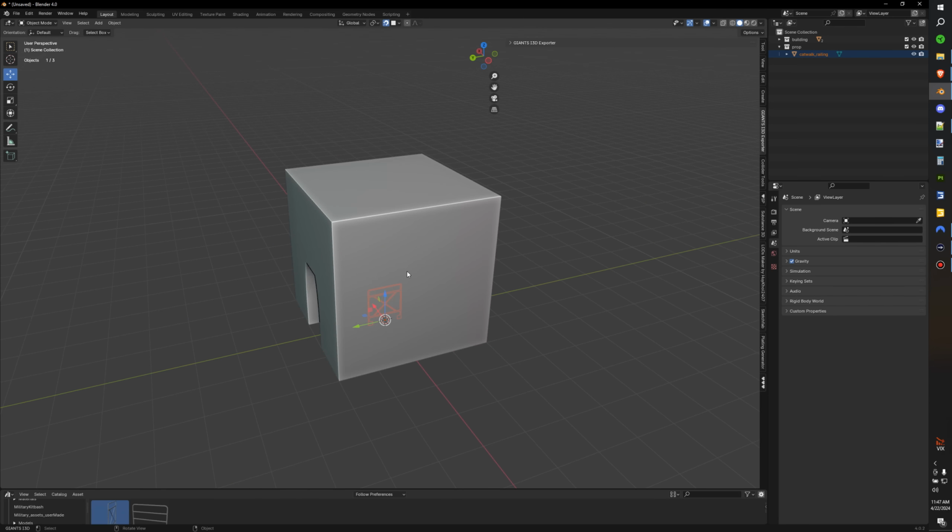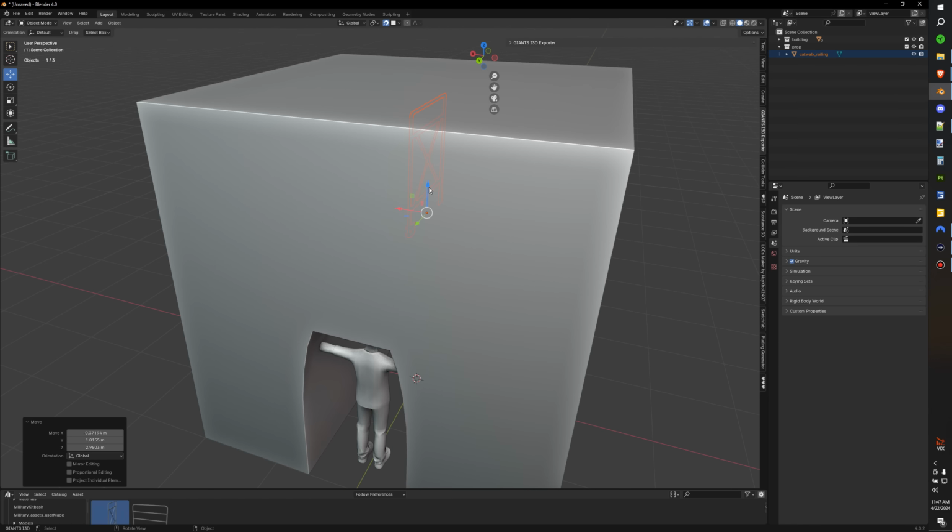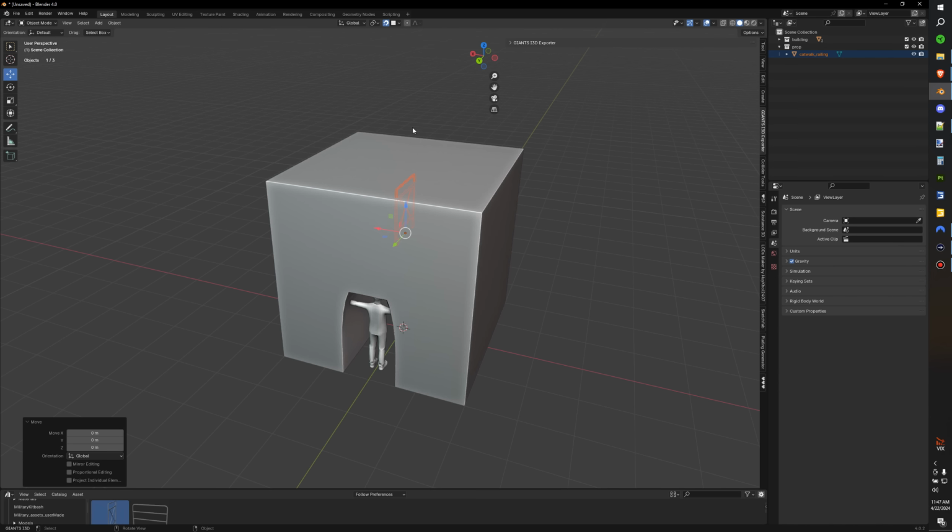We want it to be up here. So if you press G, G will allow you to grab it and put it anywhere. We actually want it to be up here, but it's being weird, right? It's snapping, but it's being very odd. So we're going to change some snapping features here because we want this to snap at the base, not at the rest of it. So we're going to unselect that.